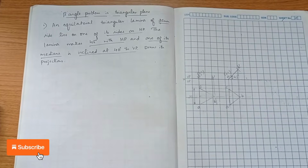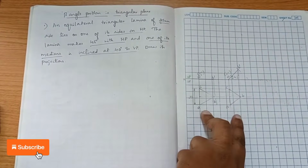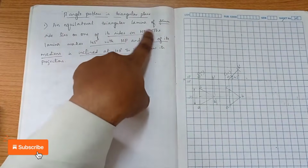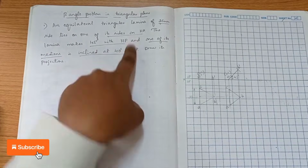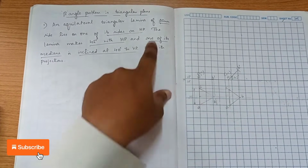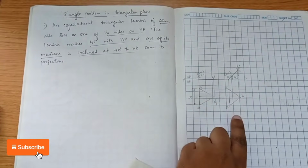In a beta angle problem, the first two positions will remain the same. That's why I have drawn the first two positions here. You can see an equilateral triangular lamina of side 25 lies on one of its sides on HP. So we have constructed the first position, top and front view. Next, the lamina makes 45 degrees with HP, so the 45-degree inclination is also shown here.